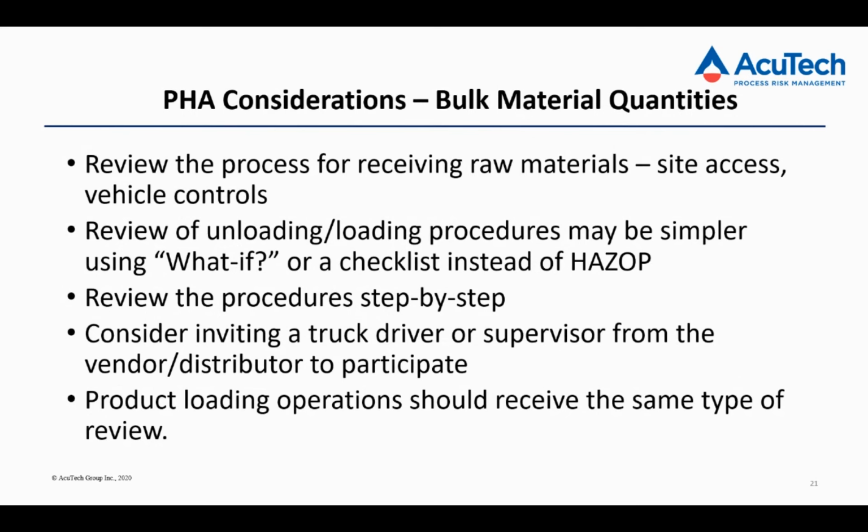I'd like to give you a couple of additional thoughts for your PHAs, your process hazards analysis, when you're unloading materials, or for that matter, you'll see when you're loading materials. These thoughts can be rolled into your HazOps. You're doing hazard and operability. You can create a checklist to cover some of these unloading issues and pull out that checklist, walk through it every time you do an unloading operation in your plant.